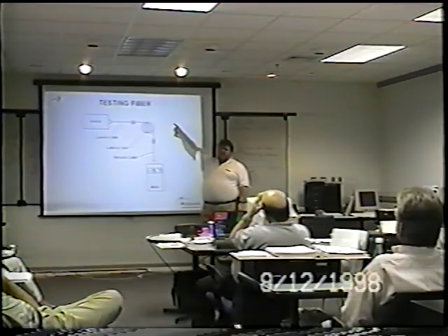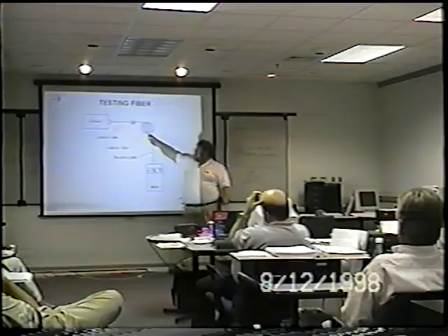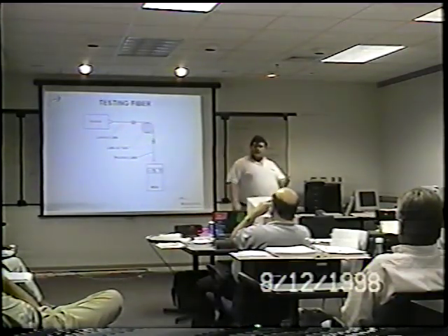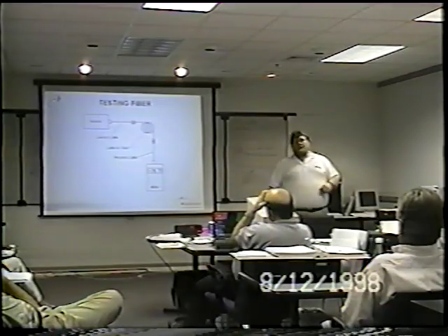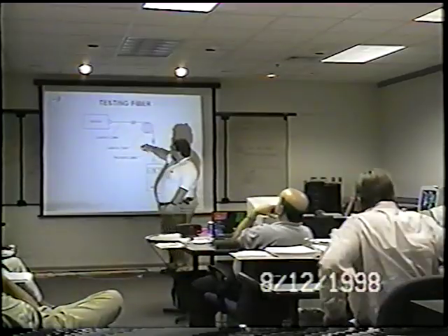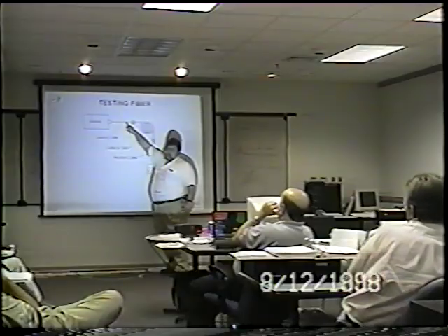The types of emitters in these devices, especially in multi-mode, you need to launch this into fiber first and launch cable for what we call modal conditioning and for repeatability. Because once you do that, I plug this receiver into here, I can set up a known benchmark for that link fiber there.